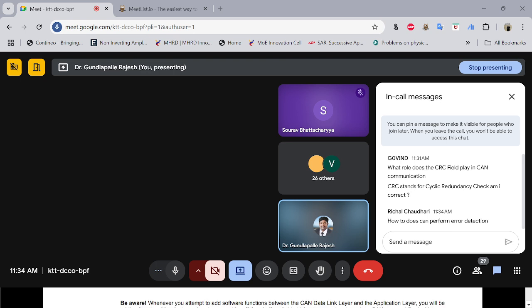Now the implementation of the CAN. Usually we have a physical layer, data link layer, network layer, transport layer, session layer, and presentation layer in any normal network. Whereas for the CAN, the network, transport, session, and presentation layers are combined together. We call them higher layer protocols. So only four layers will be there for us: physical layer, data link layer, higher layer protocols, and application layer.